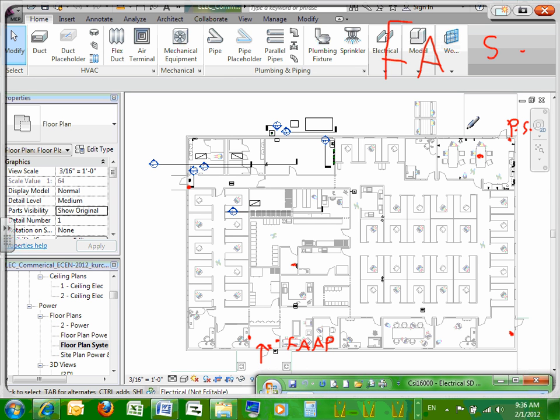If Chad handed these out, I think there might actually even be a template. I know there's a template in CAD. I don't know if they have a template in Revit or not, but it'd be pretty easy to make one, to lay out your horn strobe so you have complete coverage. It all depends on which candela you specify. Candela is the brightness of the strobe.